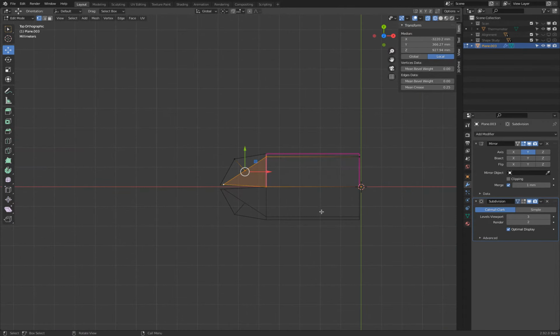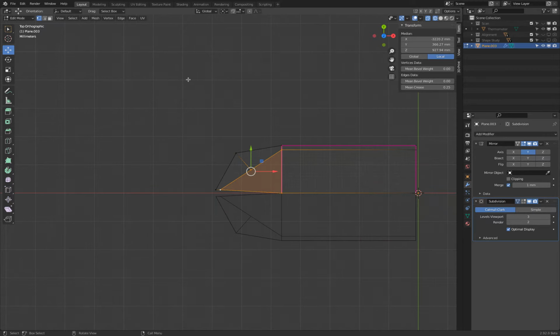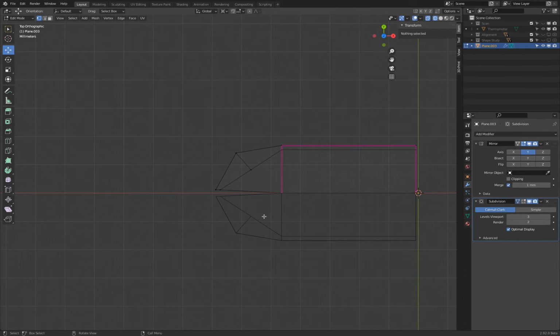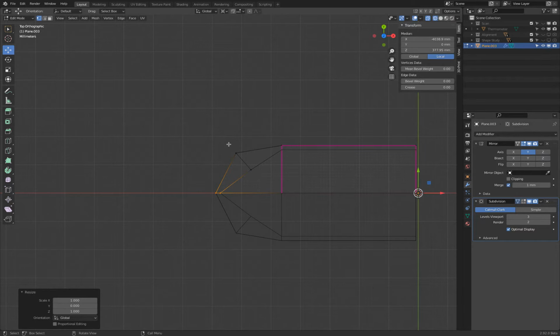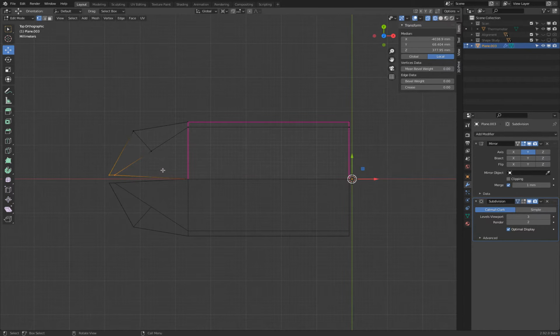So how do we fix this? The 3D cursor will come in very handy here again. Shift S cursor to world origin. Then transform pivot to 3D cursor, AA. B, select these 2 points. And then we say S along Y-axis to 0, enter. There we are. Let's do this one more time. S, Y, 0, enter. Very good.